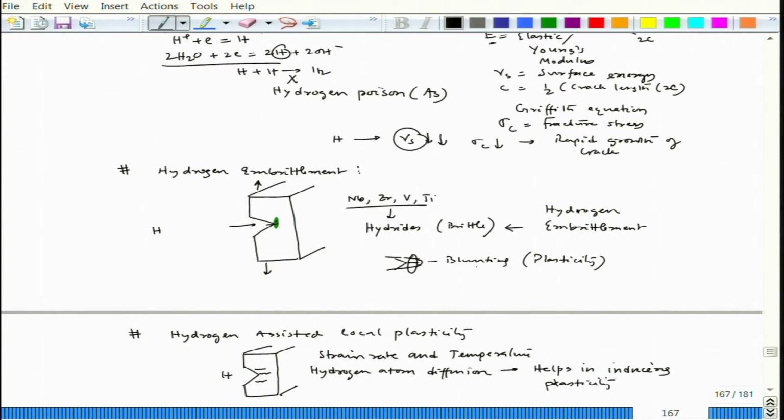Okay. If it is plastic, then definitely deformation would happen, and the deformed zone can also get dissolved because that is an active zone. That way the crack gradually progresses due to hydrogen atom diffusion, leading to plastic zone creation, and that happens very locally around this zone, and that zone is getting deformed due to the triaxiality of the stress at the crack tip.